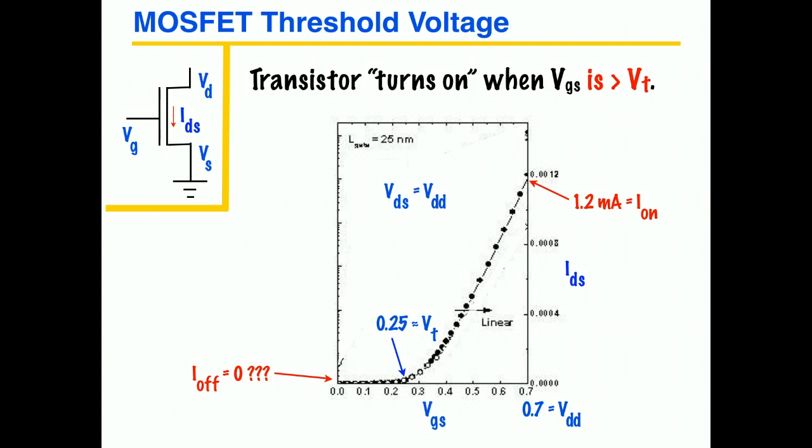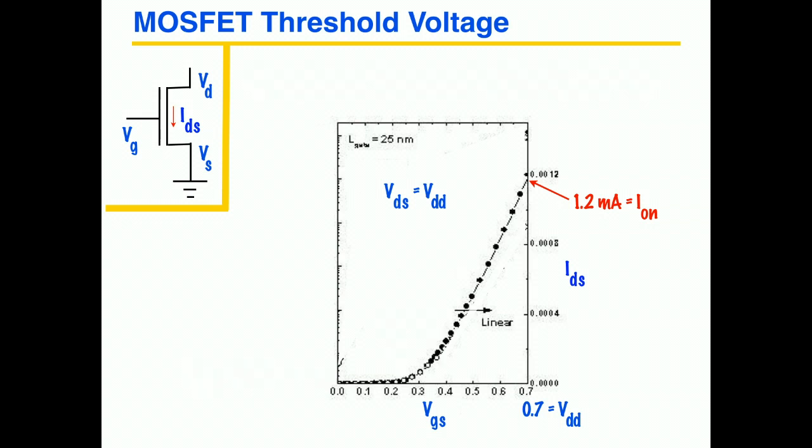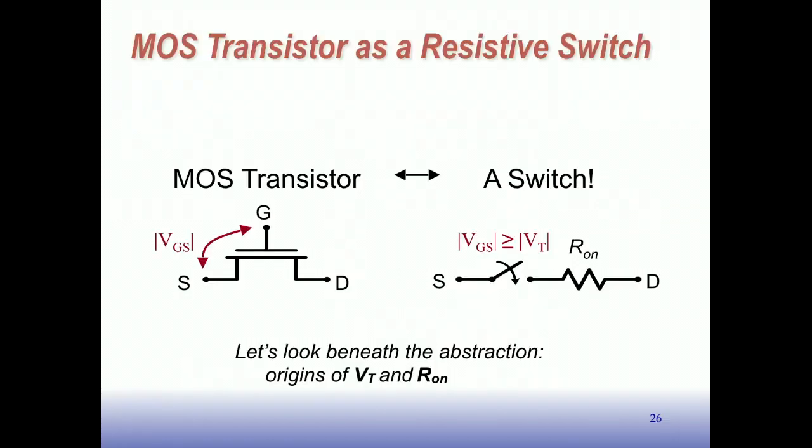The other thing I want to talk about is the idea of modeling a transistor as a resistor. And we like to do that. We really like this picture, as you'll see next week, and you'll be very happy that this is just a resistor, because then all the analysis of the timing of CMOS circuits gets very simple. We can do it all with first-order differential equations, just RC circuits, which you've studied before in other classes. So we like to keep that as a resistor because then we have this kind of linear analysis.